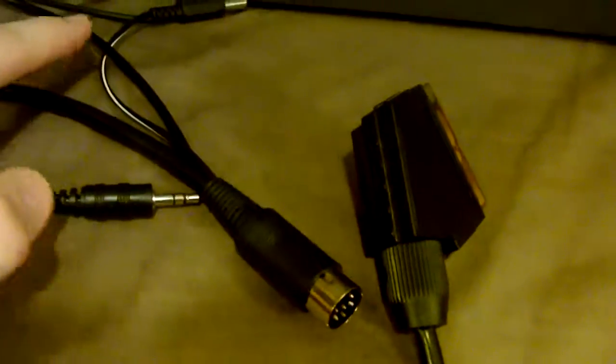So what this special cable does is, on the one end of the cable is just the SCART connector. On the other end, we have the RGB video connector, which of course goes into the computer, like I said. And we have, coming out of that connector, this audio cable. So this goes into the audio port on the back of the computer. It feeds into this cable. It doesn't actually go to this connector. It just goes through the cable like that and out to the SCART connector to give you the audio in the SCART connector.